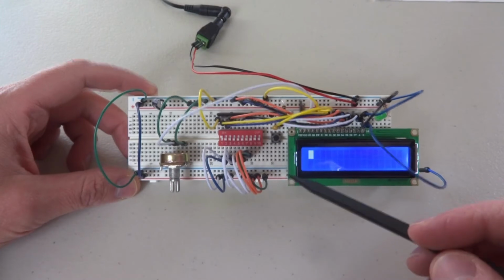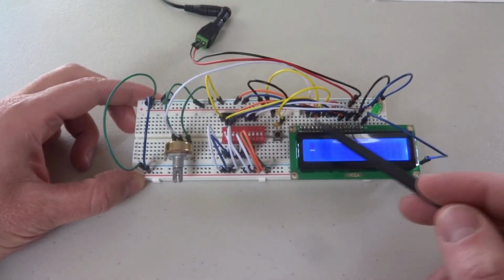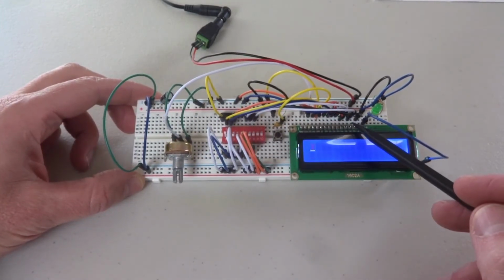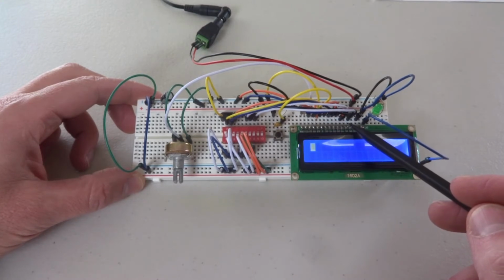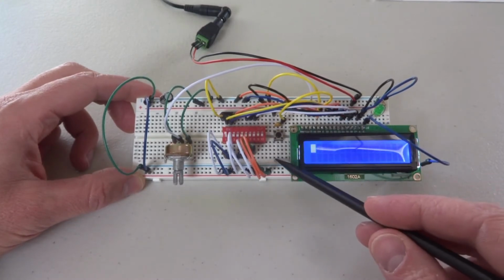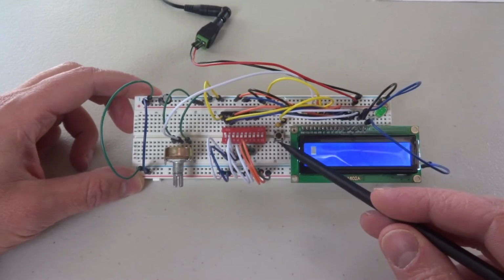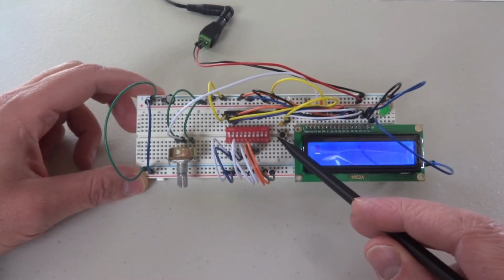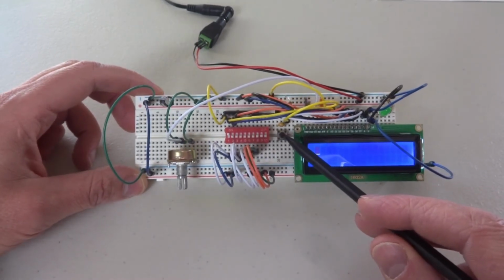It has 10 switches. We're using the LCD in 8-bit mode, so we're only going to use the switches to send 8 values. It's a straightforward process to set the dip switches. Next to the switch is a button. We've connected the LCD to the enable pin to send the values of the dip switches.